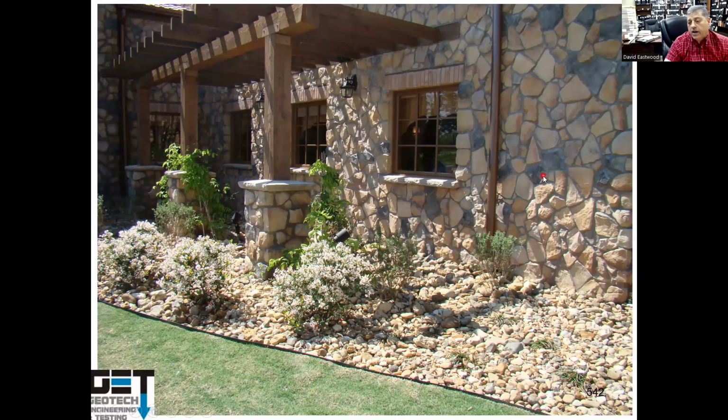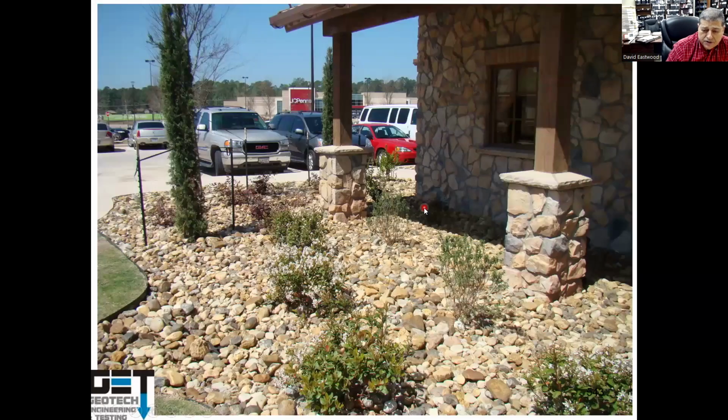It's got rock exterior, which means that if there's any kind of movement, you're going to get cracking. It's very, very stiff material with mortar. So I started taking pictures. The manager asked me, why are you taking pictures of my building? I said, man, you got really bad landscaping here. If the building starts moving, you're going to get cracks developing in the walls and stuff. So I'm taking initial pictures so that when it cracks, we have some initial pictures of it.